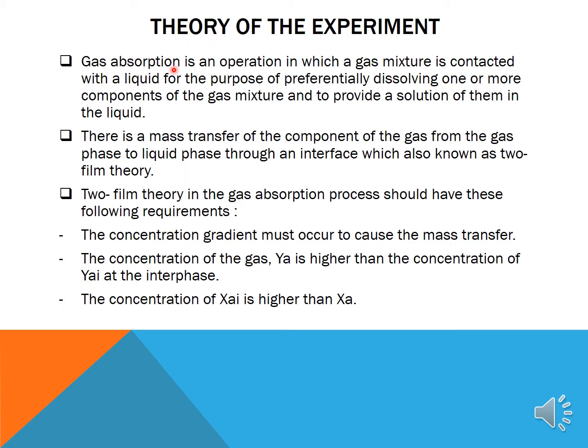Gas absorption is an operation in which a gas mixture is contacted with a liquid for the purpose of preferentially dissolving one or more components of the gas mixture and to provide a solution of them in the liquid. There is a mass transfer of the component of the gas from the gas phase to liquid phase through an interface, which is also known as two-film theory.